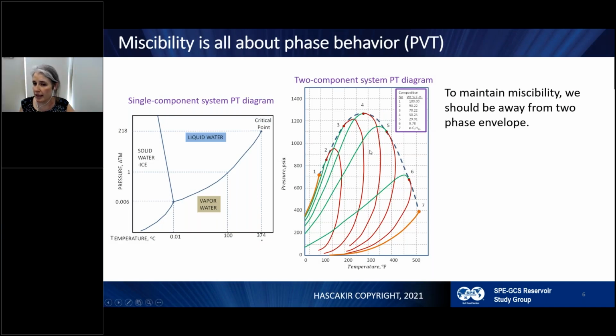And then we are seeing their single component system phase diagram. This is the vapor pressure line for ethane, and this is the vapor pressure line for heptane. And in these two, we may see the different percentage of these two components. Okay, so we may have 10% of C2 and the remaining can be C7, and we will have a phase envelope which will just give us the two-phase region. Two-phase region means that I will have gas and liquid in the system.